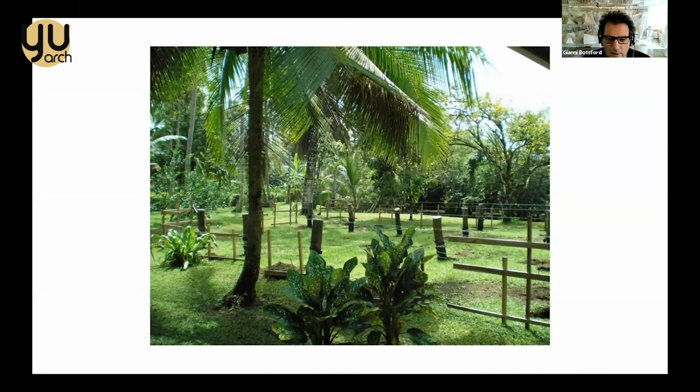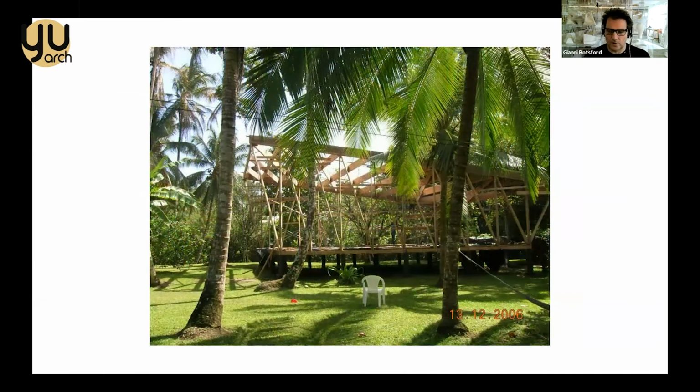So the site starts off with putting the timber piles into the ground, which are cast in. So you can just see them there being set out. And then the superstructure emerges out of the ground. And one thing I really enjoy with this photograph is that there's very little evidence of construction. There's no damage to the ground. It's touching the ground very, very lightly. And timber's a very versatile, relatively light material that you can work easily in different conditions without having a lot of other infrastructure to make that possible.